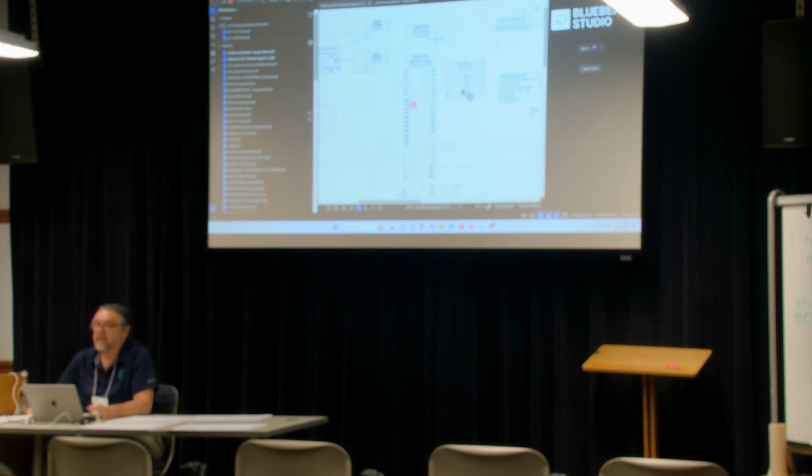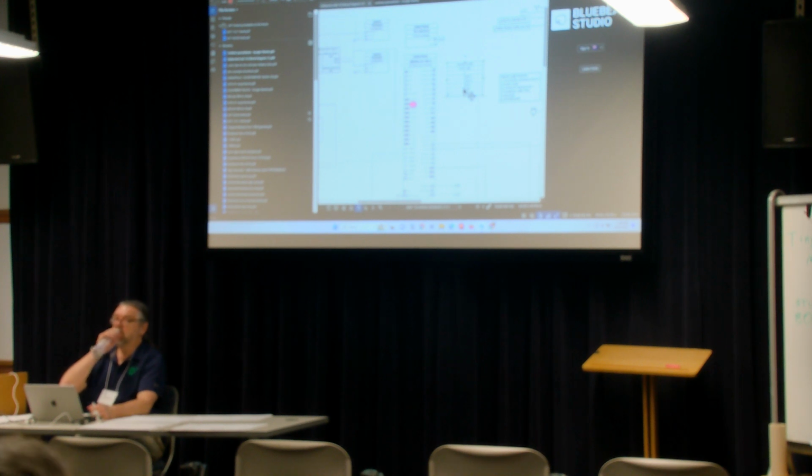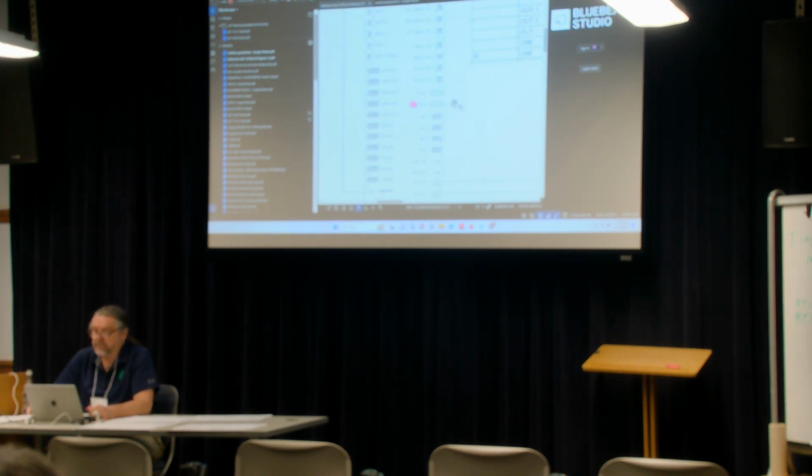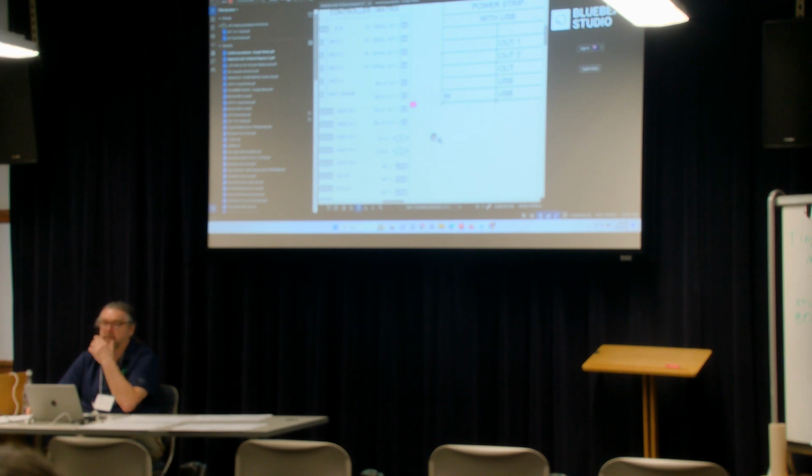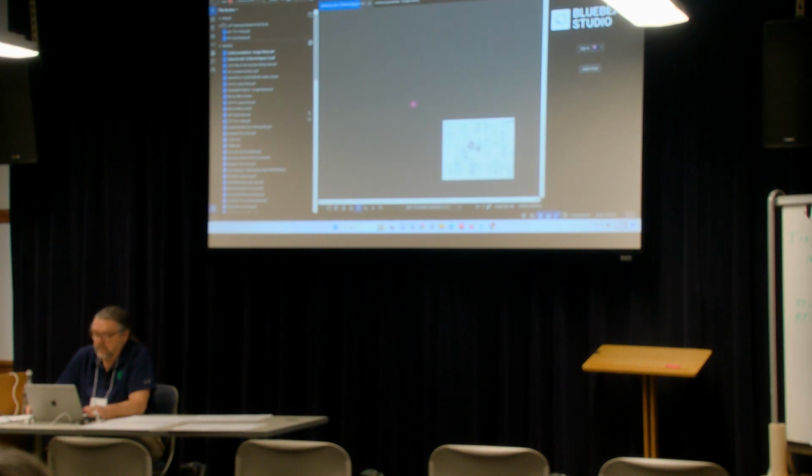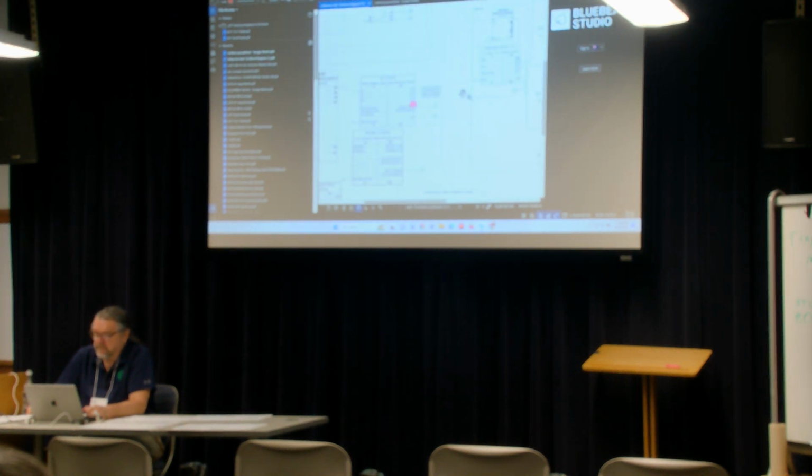One thing, in my experience making blocks, I really do like to put the exact same text that you're going to read on the device and the connector type on there in this pictographic format. If you're working with student workers or people who aren't at an engineer level, you can have a block and just put some lines, but to have a little bit of something that's going to ground this abstract drawing into reality, I think is worth the time and effort. But if you have a pre-made library, you can do all your stuff with that.